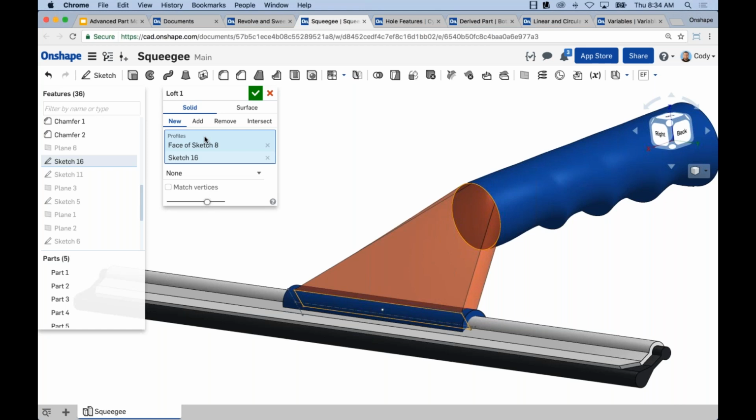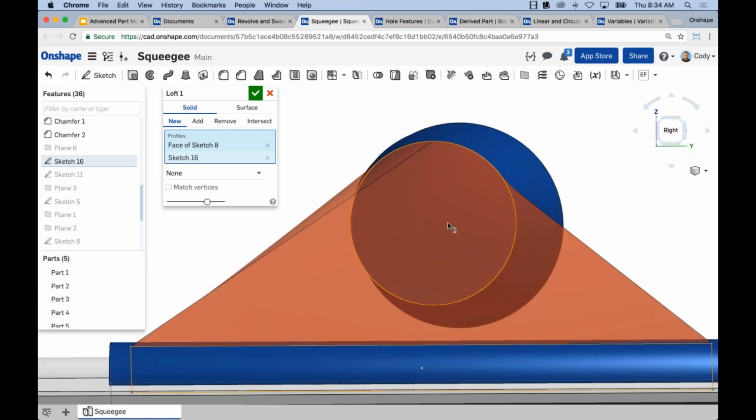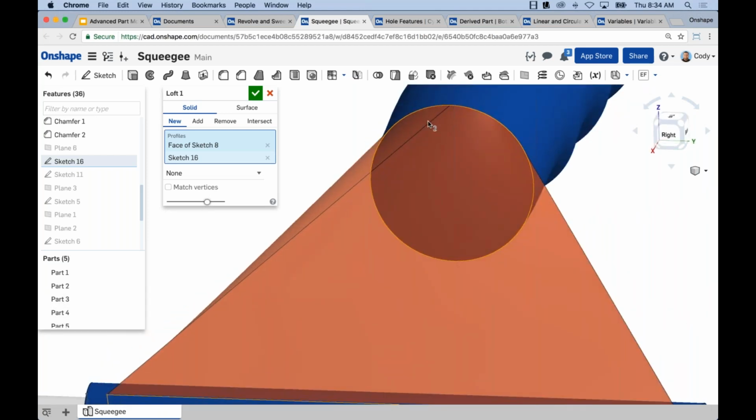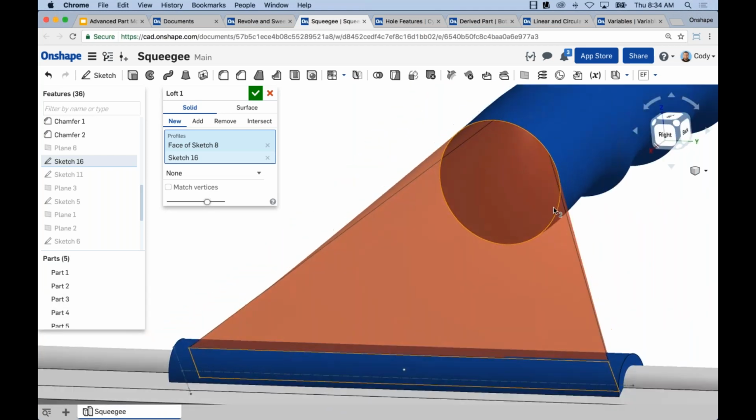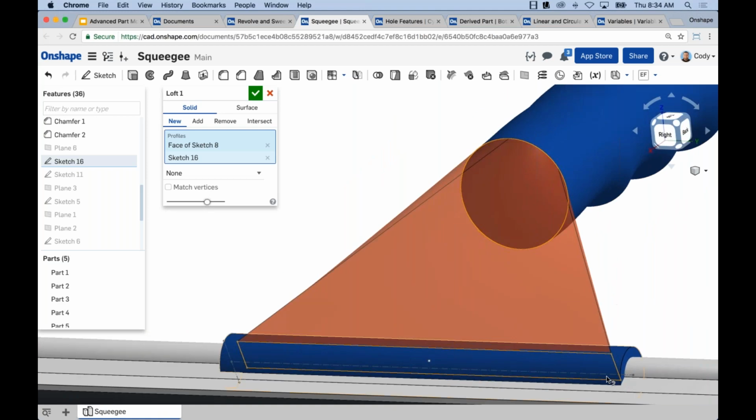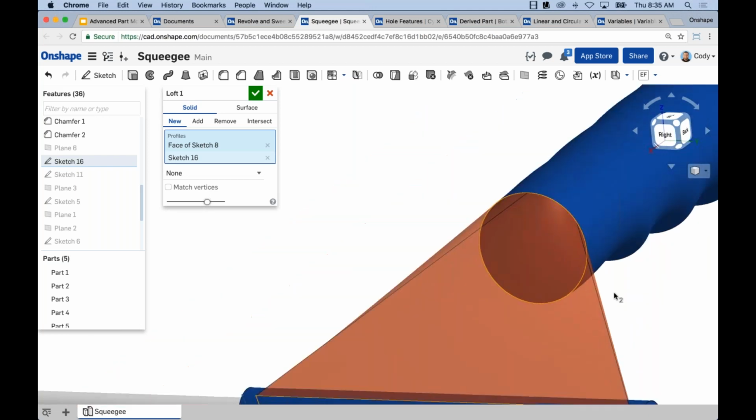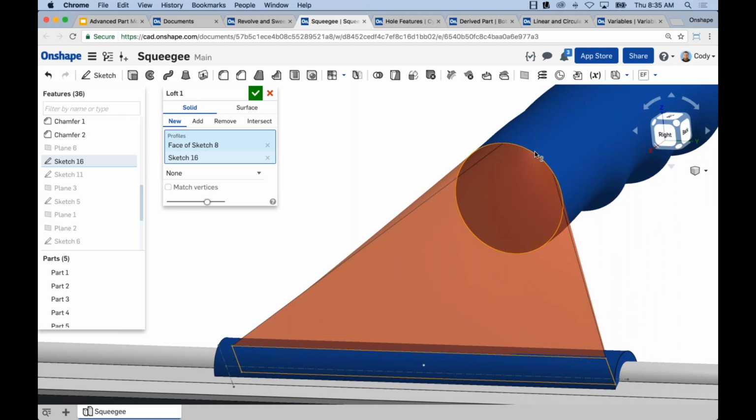But as I mentioned before, by default, it assumes a lot of things in the loft command. So if we take a look at this loft, you can see where it's joining the two. I'm going from a circle to a square, and it's not immediately clear how these should line up. What I mean by that is you may have twist, where I would rather this top point of my rectangle line up somewhere up here and not down here where it is.